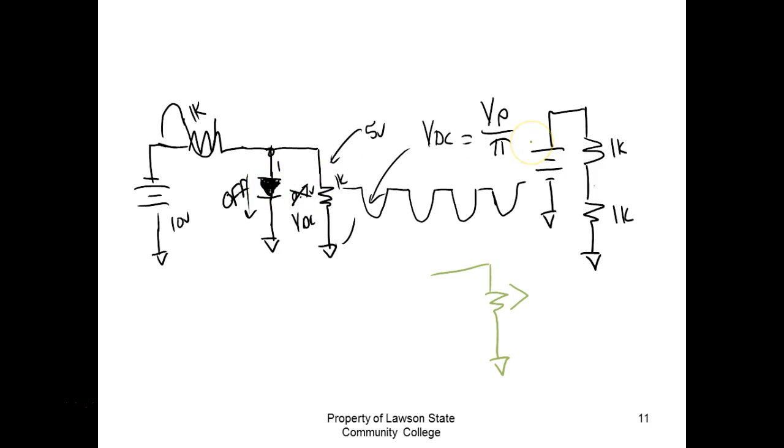This guy here is acting like a switch. That's all it's acting like, a switch, except it drops 0.7 of a volt. So how you hook control devices does not determine whether it's a series circuit or a parallel circuit. It depends on how the loads end up, right? That makes sense? So we switch from a 1 resistor circuit when it's forward bias to a 2 resistor circuit when it's reverse bias. So good question. That's a good circuit, guys. A while ago I said we get the full peak voltage. That's not true. When it's reverse bias, we get the 2 resistor series circuit.